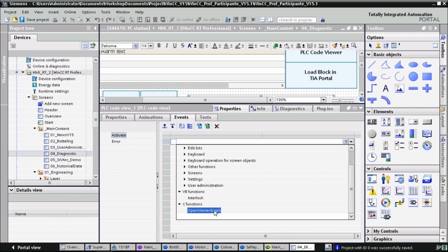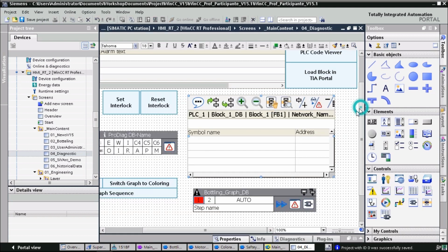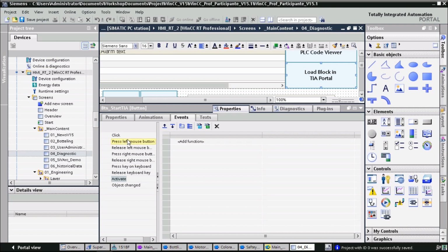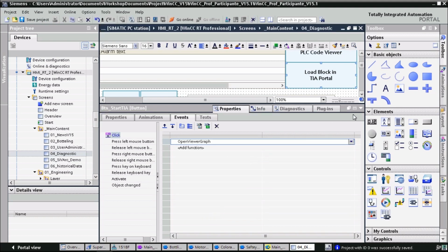That's how ProGuide basically works for alarm handling. The biggest difference is that the alarm handling is basically done in the PLC, so you don't have to create any alarm messages in WinCC. And you get the actual timestamp from the PLC right away.